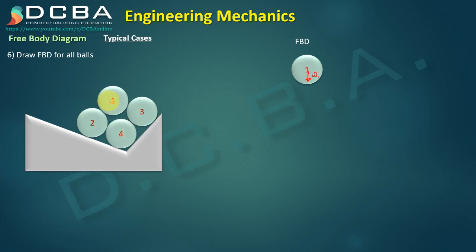Second, now this ball is resting on the second ball and third ball. The moment it comes in contact with the other two surfaces, as I told you, they are going to give a reaction, and the reason this ball is resting on the second and third ball is because the second and third ball are giving reaction to the first ball. So these are the two reactions, R2 and R3.